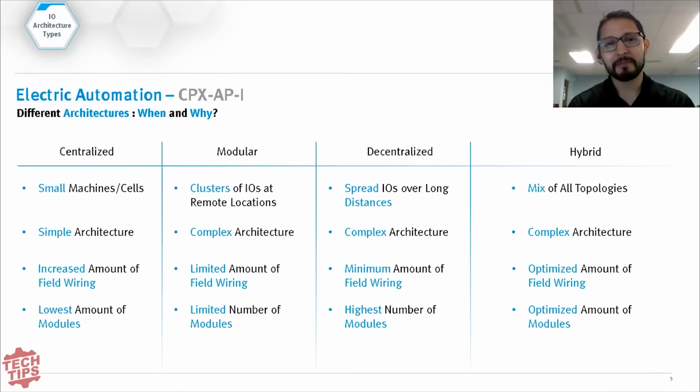So those were kind of my thoughts as you were going through that. We do see these everywhere because of different needs. Right. And you were talking about mainly the third point there on those lists. And I've seen this all around, like companies preferring to use M12 and M8 connections because they're super quick. You just get the cable pre-assembled and you can just connect the sensor. While in the past, when you were, for example, wiring a multi-pin valve manifold with a sub D25, as you mentioned, you will have to terminate every single wire, and you multiply that by how many valve manifolds you have, it starts adding up, right?